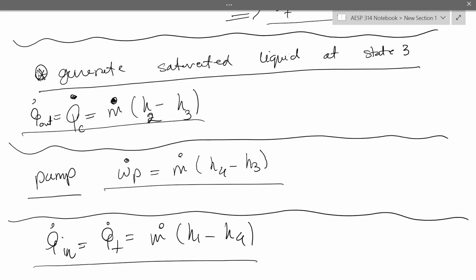Do you always need a condenser, or can you just have like a large reservoir as well? What does a large reservoir going to do? So you essentially put the water back into a reservoir and then pump it into the boiler, right? From like the bottom of the reservoir, so it's cold. As long as it is in saturation condition.